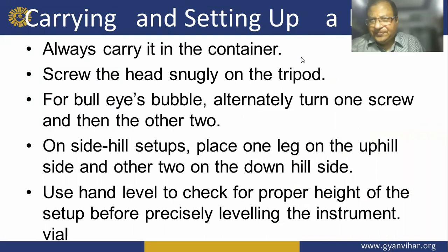Carrying and setting up a level. Always carry it in the container. Screw the head snugly on the tripod, centering the bull's eye bubble. Alternately turn one screw and then the other two. On a slope, place one leg on the uphill side and the other two on the downhill side.